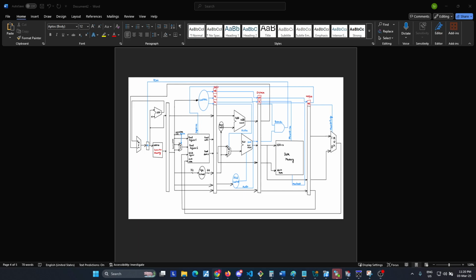The purpose of this lab was to create an ARM-compatible processor core in NetFPGA and to have bubble sort run on it, sort the array, and put data back into the data memory. The first thing we did was create the assembly code for the bubble sort, followed by creating the binaries for it.